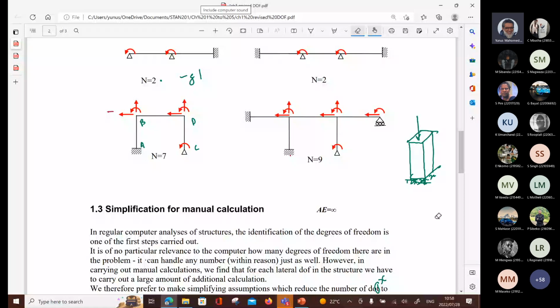Vertical, no. The reason is that in relation to the load, the size of this member, it's the way it's made up. It's infinitely stiff in relation to its length. If you had taken the same ruler and made it 10 meters long, and then you put that point load, what could possibly happen? Yeah, it's 30 centimeters or 300 millimeters long in the physical model that you have in front of you. You put a point load on it.